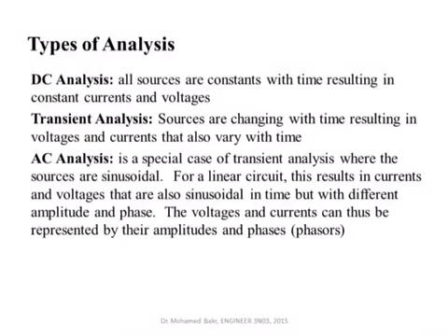So I'm going to repeat this again. A phasor is nothing but a representation of a sinusoidal signal. If you have a linear circuit and your source is sinusoidal, then the currents and voltages everywhere in your circuit will also be sinusoidal with the same frequency. They will only vary in terms of amplitude and phase. So the amplitude and phase information, we combine them together to create what we call a phasor. So the phasor contains the amplitude and phase information about different electrical quantities, including currents and voltages.